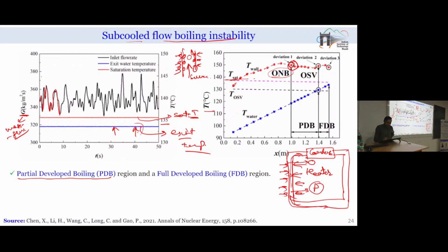However, this bubble will not be able to sustain, but then we again find that after this decrease, the wall temperature has again started increasing. What does it mean? That bubbles are forming, and these are not just collapsing at the moment, but these are growing at the moment. So, once these start growing, it means we can say that our saturated boiling has started. Okay. So, this is how we can distinguish the regimes between nucleate boiling and saturated boiling.